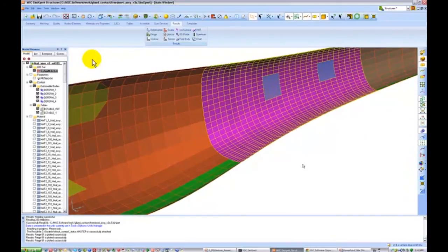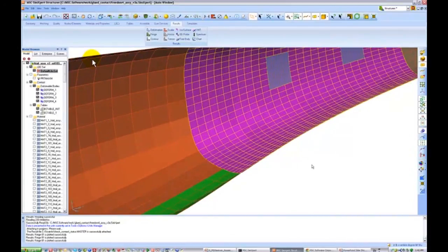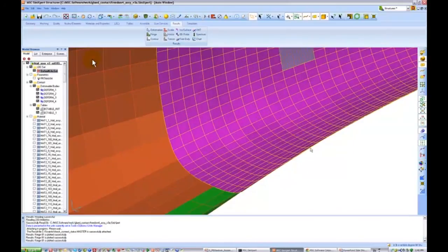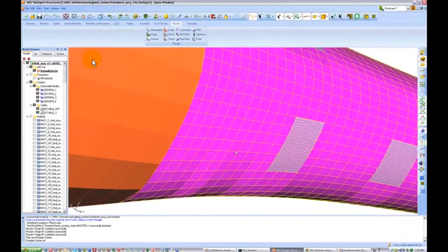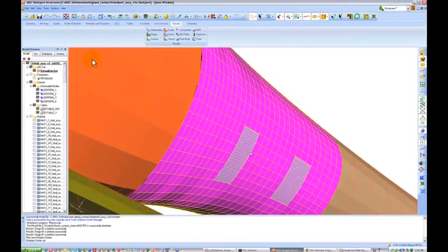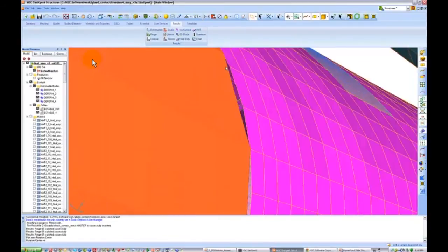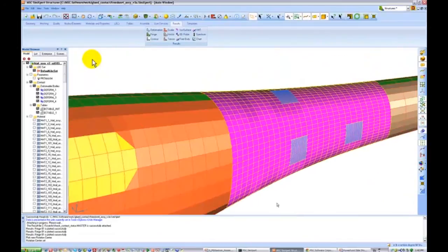And we see that we have the ability to stitch these edge-to-edge glued contact shells. We can even take care of the fact that the arc of the coarse model has a different edge, and it creates some little gaps there. But this is all captured. These can be controlled by the tolerances of the contact, and the algorithm allows us to make a very nice, smooth glued contact edge there.